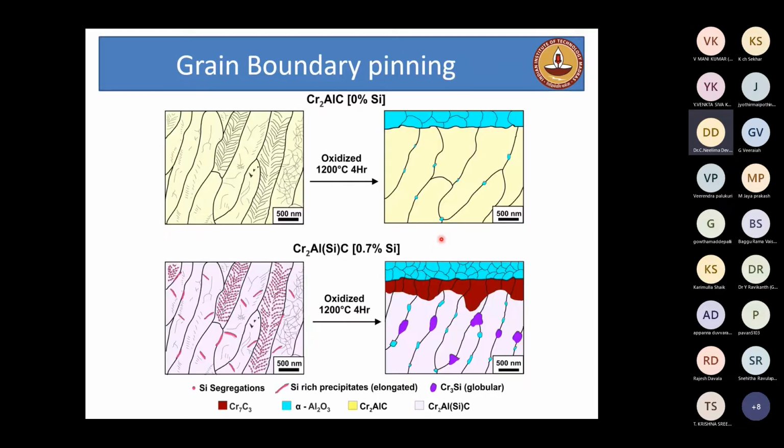If we now summarize all of these together, by combining the information that we got from atom probe and the information that we got from TEM, you can see we have V-shaped defects in the as-prepared thin film, which has nanocrystalline grains. In the without-silicon case, the V-shaped defects were present, which got annihilated upon annealing, and only the oxygen went across the columnar grain boundaries, and aluminum went out to form the oxide layer.